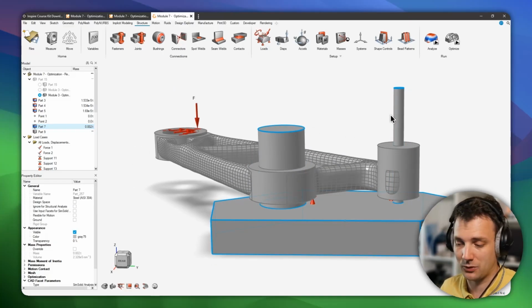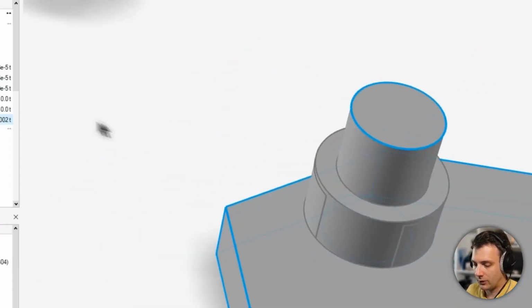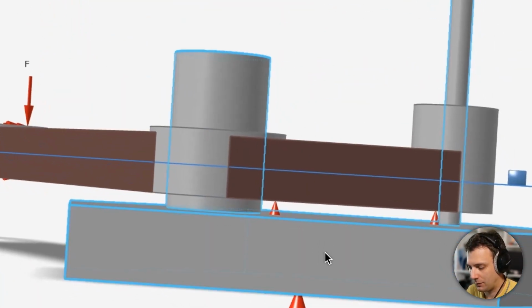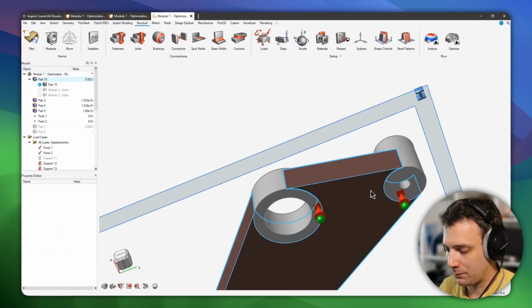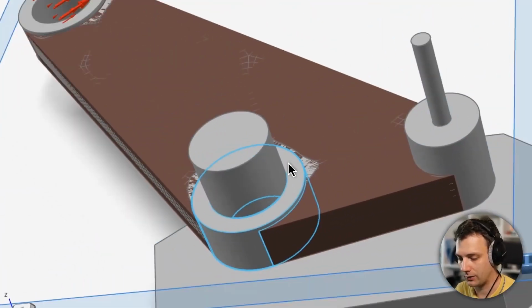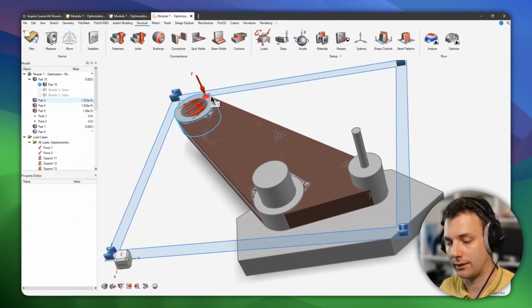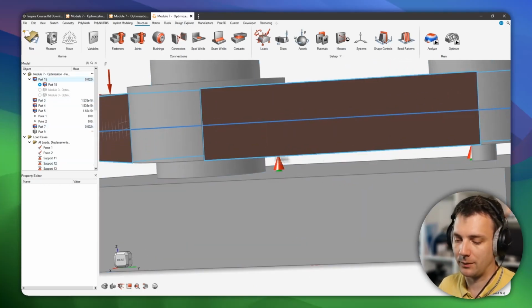That depends completely on the situation. What this part should look like, right? So this is being done then, and what else is also important to do, besides constructing this part, is that you prevent the motion in set somehow, because as you saw, I did lose all my constraints here. So there's no constraint which prevents the motion in set, which I have in load case 1. So basically it's an unconstrained model, and that's why I should have something like this bearing, or I should have moved the surface up here and did a contact here.